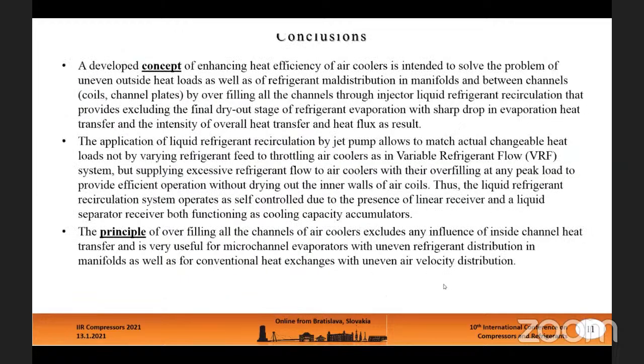Conclusions. A developed concept of enhancing heat efficiency of air coolers is intended to solve the problem of uneven outside heat loads as well as of refrigerant maldistribution in manifolds and between channels by overfilling all the channels through injector liquid refrigerant recirculation that provides excluding the final dry out stage of refrigerant evaporation with sharp drop in evaporation heat transfer and intensity of overall heat transfer and heat flux.